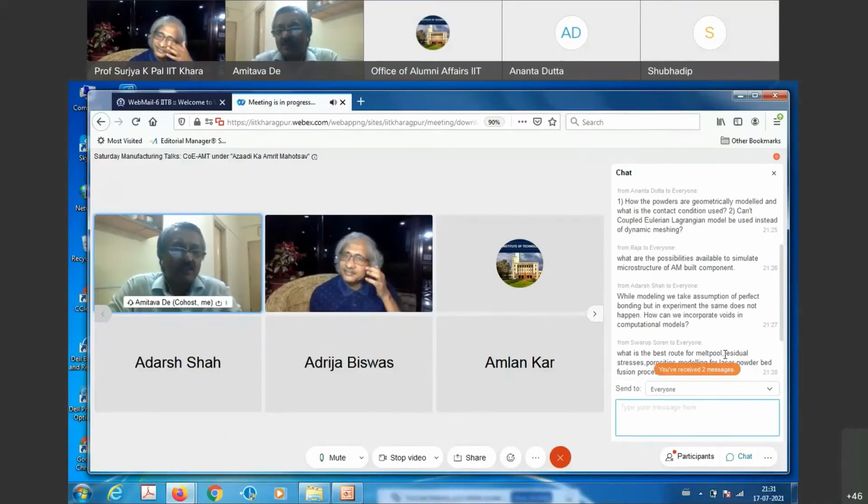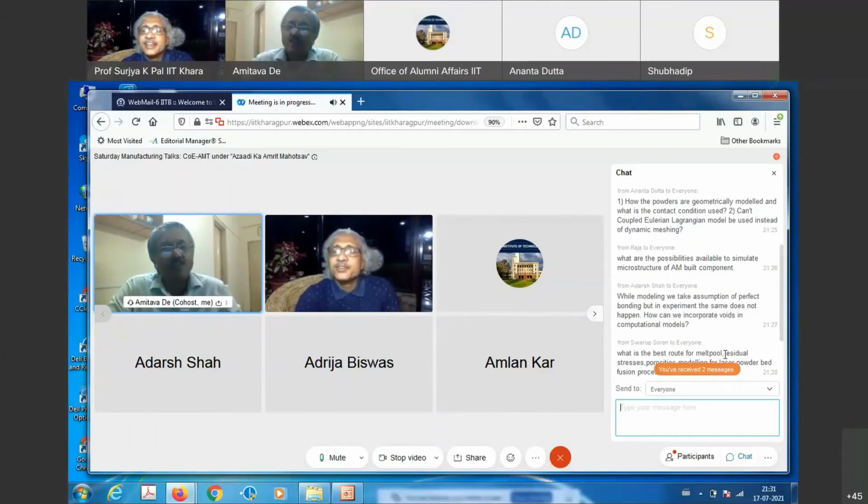Here the purpose is, imagine a situation where we do not want to use a fine mesh all throughout. People want to use the fine mesh only where the local calculations and local results are important. Okay? So this is all that is required. Whereas an Eulerian-Lagrangian model is not really localized. You don't really look at a very localized model in that sense.